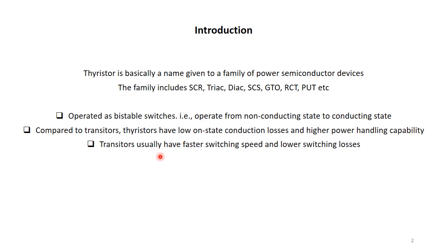This power semiconductor device is a bistable switch, which means it blocks the voltage and current both in the reverse mode as well as in the forward mode, and it operates from non-conducting state to the conducting state by the application of a gate signal.